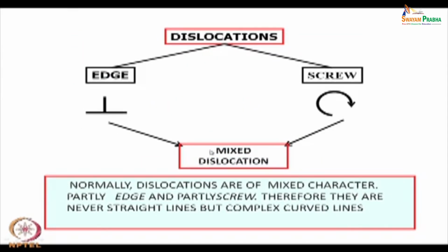So, these are the two dislocations, the nature of dislocation. One is the edge dislocation, represented by this symbol, two lines joining perpendicularly, because the B vector, the Burgers vector, is perpendicular to the T vector, the line vector of the dislocation, whereas the screw dislocation is parallel and is represented in the form of a circle, a half circle or incomplete circle.